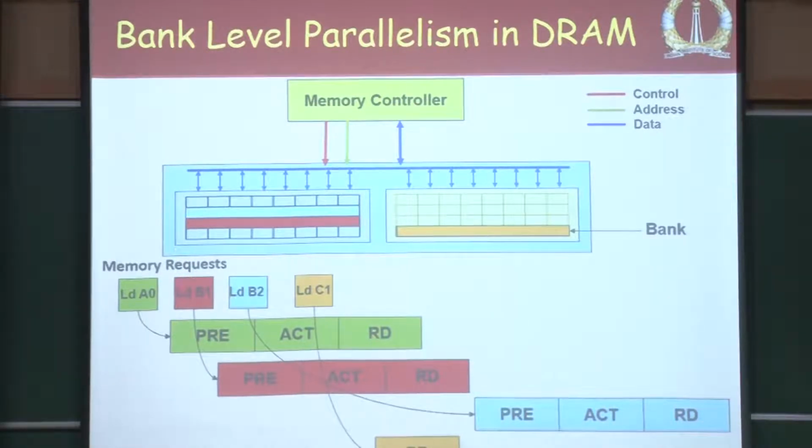so there is some kind of a device level parallelism which I do not talk about. When this particular device bank 0 is being accessed, row 0 is being accessed, that same thing happens across all of these devices in the same DIMM. That is how you get a full word. I did not go into the details. Full word in the sense that you can think of each one of these devices as having 8 bits. So, across this the word is going to be spread.